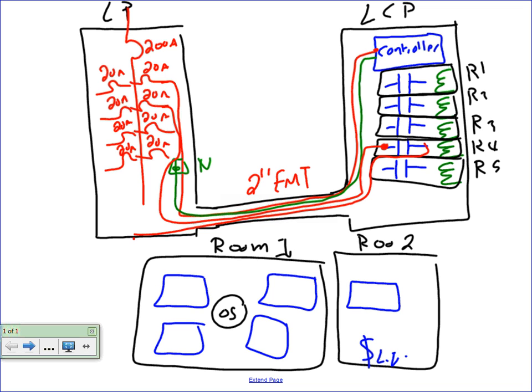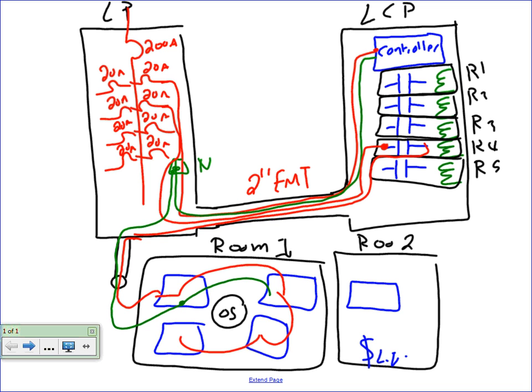And I'm bringing it now to a conduit. I have a conduit here at the bottom. Now through a conduit, I'm bringing it here, the hot, and I'm landing it here, and here, and here, and here. And the neutral, look what the neutral is going to do. I'm going to take my neutral from here through the same conduit, here, and here, and here, and here. I have just brought the power circuit into the lights through the contactor. Can you guys see what I've done?